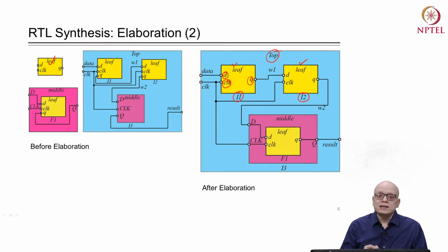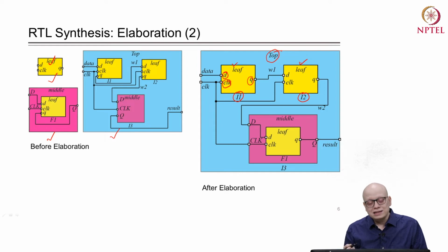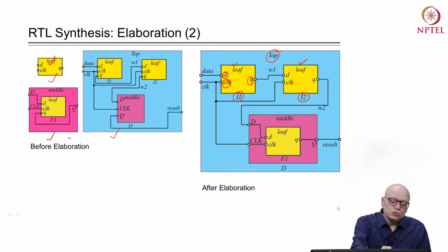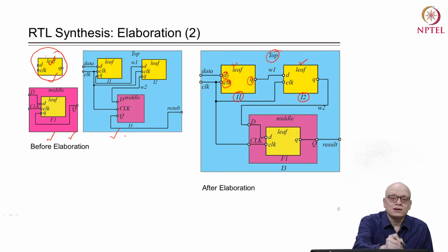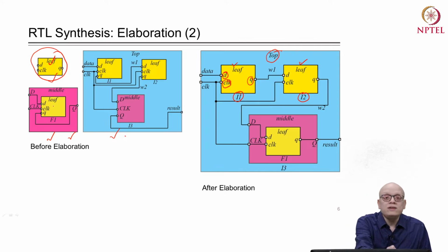Now, during this stage there can be errors or elaboration errors that the tool can report. Now, when can the error be? So, there are some common situations. Suppose while we are running the logic synthesis tool or RTL synthesis tool, these three modules were in separate Verilog files, and by mistake we gave only these 2 files and forgot to give this file. In that case, the tool will not be able to establish what this module leaf is,